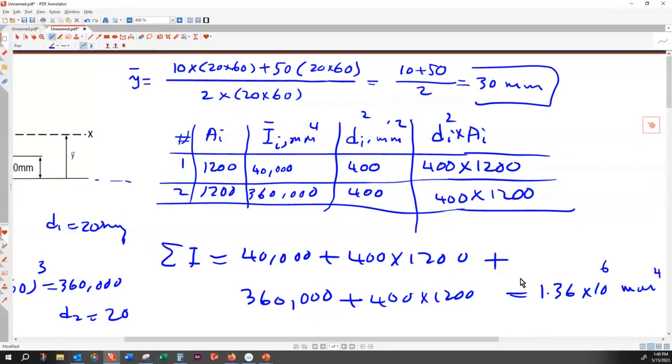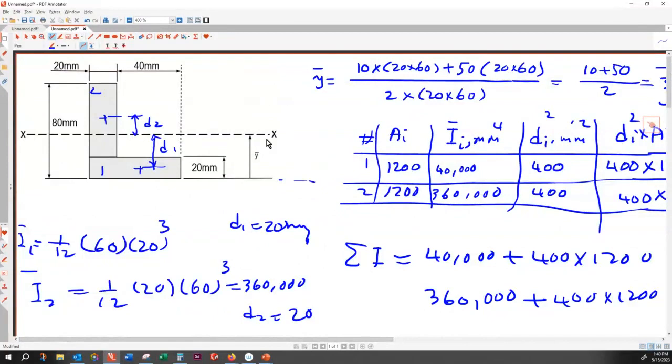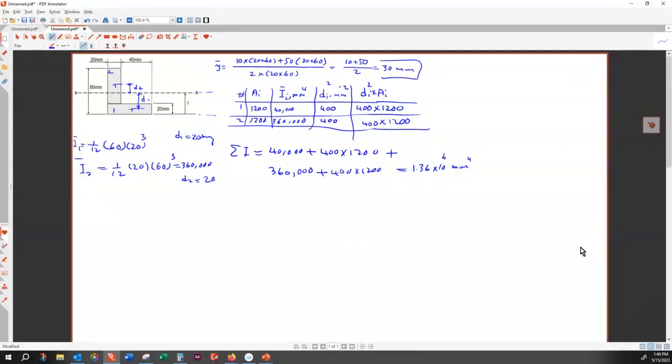All right. Now, with that section, this is my neutral plane. Let's have a closer look at the flexural formula, that is M max times y max over I. Y is for a typical point, measured from the neutral plane.